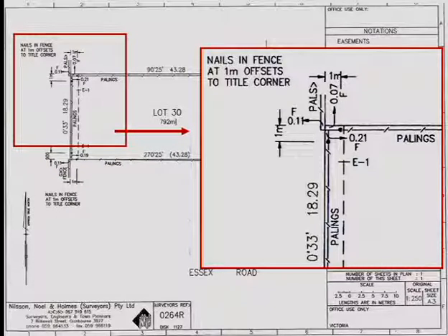And when we did the land survey, it was discovered that the fence at the back of the property, from the front to the back, was going on an angle. And at the front, it was about 100 mil into the neighbour's property. But towards the back, it was almost 600 millimetres into my client's property. And 600 millimetres is a lot.